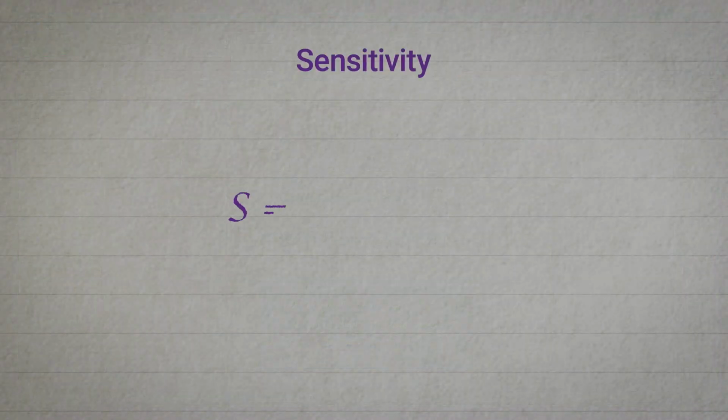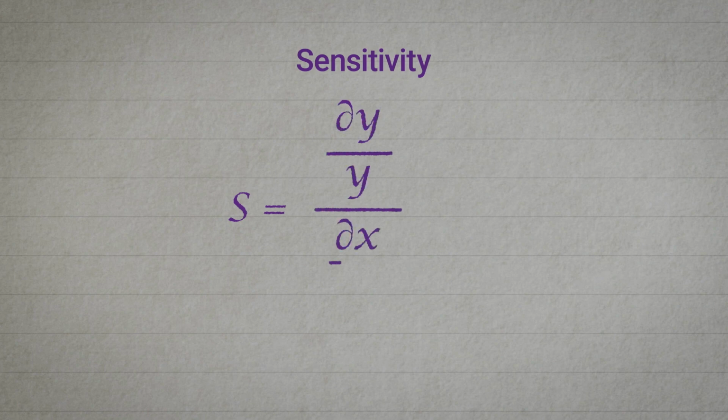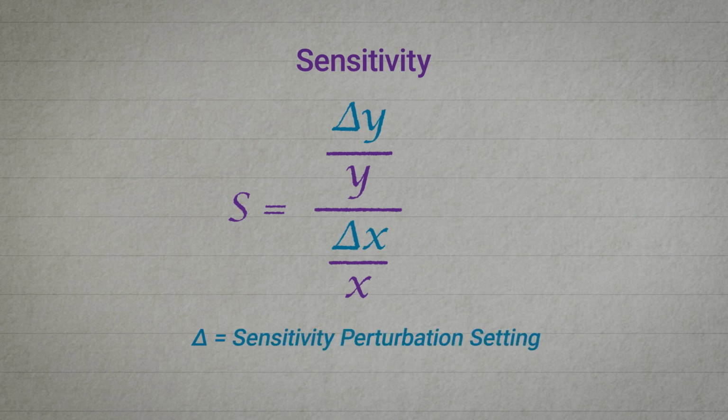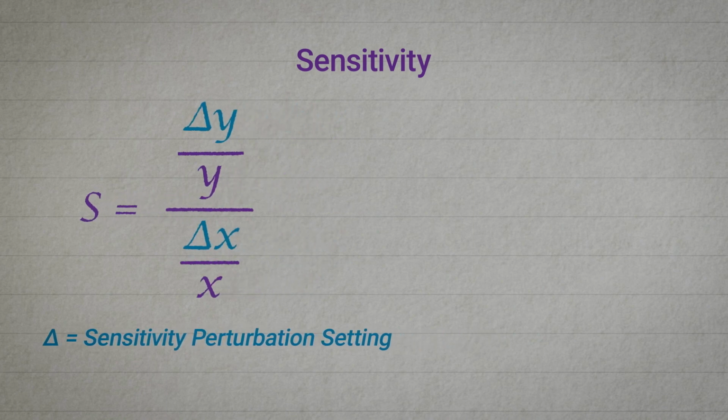A system sensitivity is the partial differential of the output with respect to an input at a fixed input point. Saber's sensitivity analysis uses an approximation of this definition. It perturbs an input, measures the change in the output, and normalizes the value. This technique enables sensitivity analysis using more complex output measurements such as duty cycle and settling time.